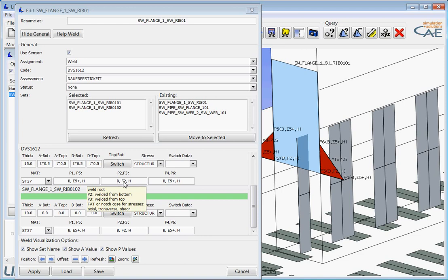The second notch case refers to the loading condition transverse to the weld direction, and H is the shear. F2 actually is the worst notch case in that code, which is used for both toes.